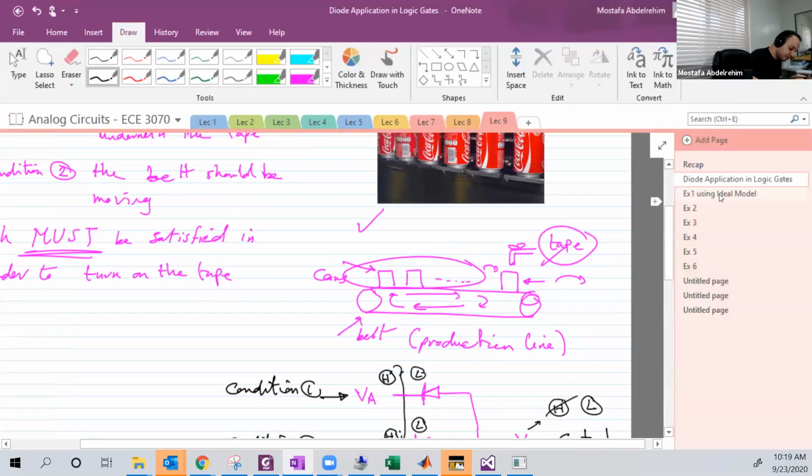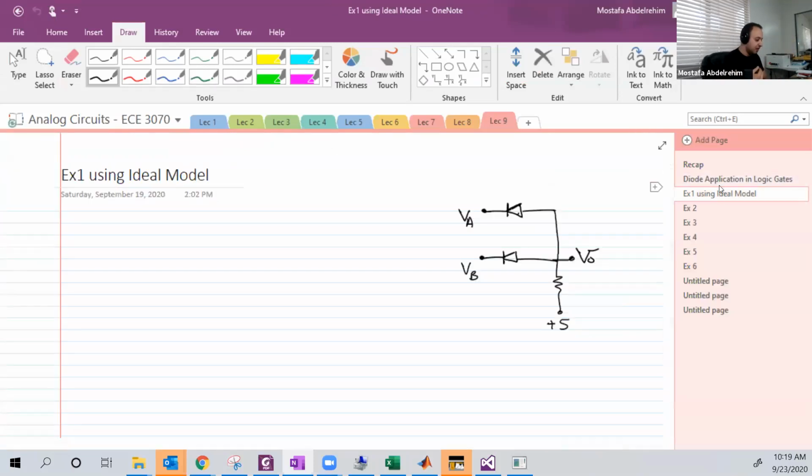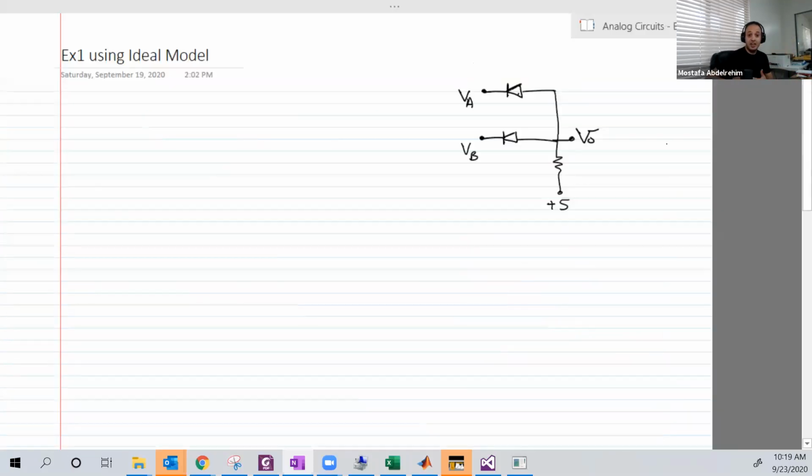Now, okay, you guys now get the idea of logic gates and logic circuits. It's just a circuit that has an output. This output can be high or low, and also the input which controls or determines the output of the circuit can also be high voltage or low voltage. And usually this high voltage is a range around 5, usually, not all the time, in most of the famous applications. And the low is usually a voltage around 0.